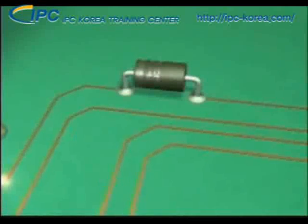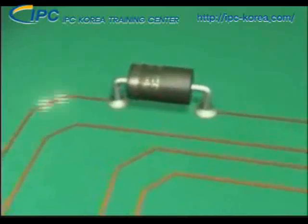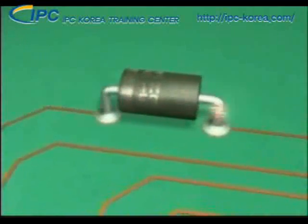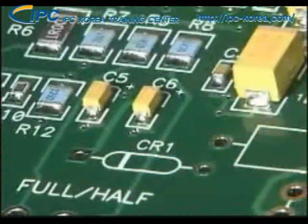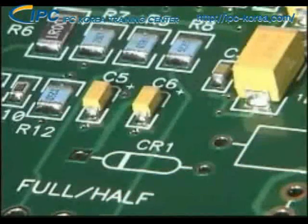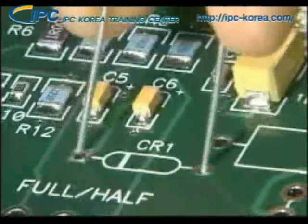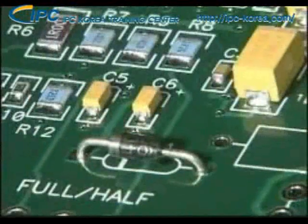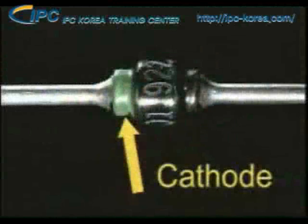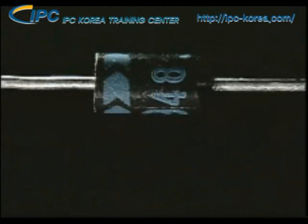Now let's turn our attention to diodes. Diodes are semiconductors that allow electrical current to flow in only one direction. The reference designator for diodes is CR or D. All diodes are polarized components, meaning it is important to install them correctly. Polarity is usually indicated by a ring on the cathode or negative end. An arrow may also point to the negative end.